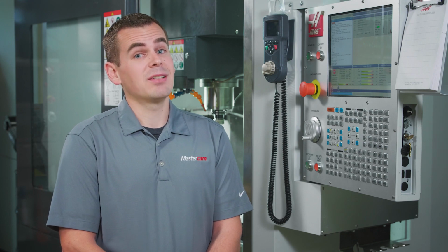Ideally, we should be looking at different settings for different toolpath types and applications. There is also setting 85, which controls the max corner rounding, which aids in acceleration and deceleration around corners in a toolpath. If you've never changed the default settings, then 191 will be set to medium and 85 will be set to 25 thousandths. These are good baseline numbers, but they aren't optimal for every circumstance, which means you're not getting as much out of your Haas CNC as you can.